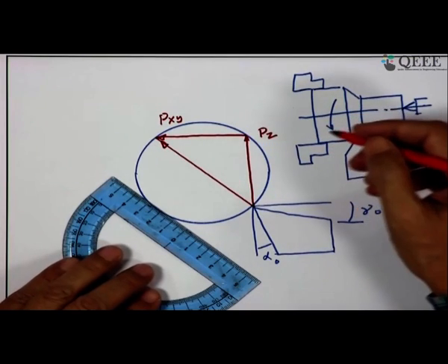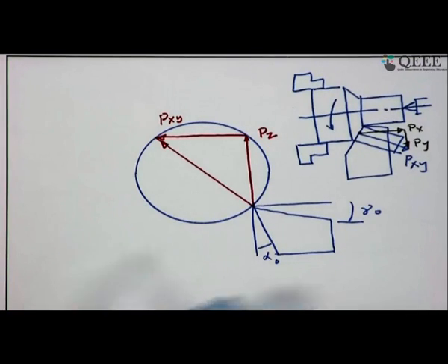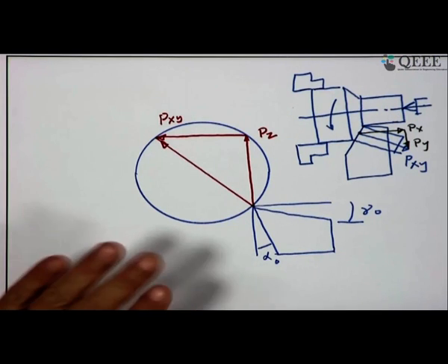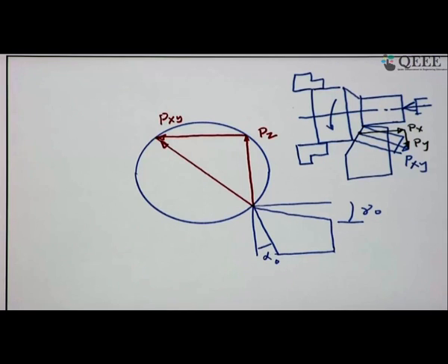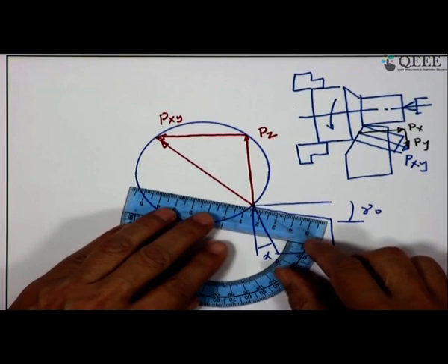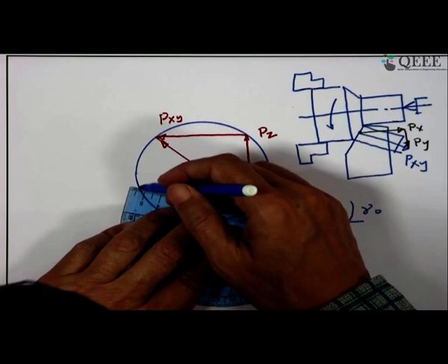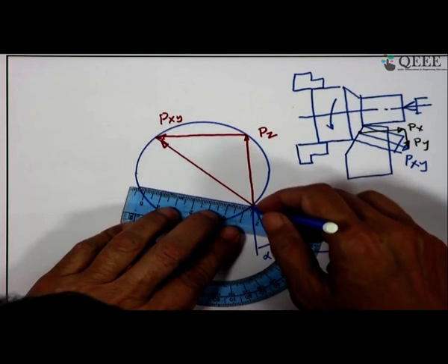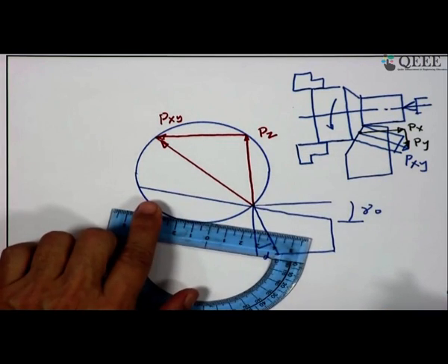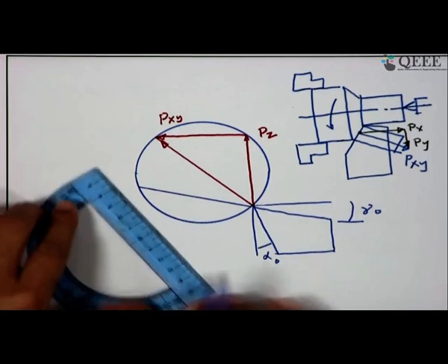that is from the tool side. It can be from the other side. So, it is action reaction. Now comes what about F and N, which are exerted by the cutting tool. So, for that what you have to do? You have to extend this rake surface. So, you extend this rake surface and you extend this line. So, you join this line. So, you get another chord length, and normal to that you draw another line.